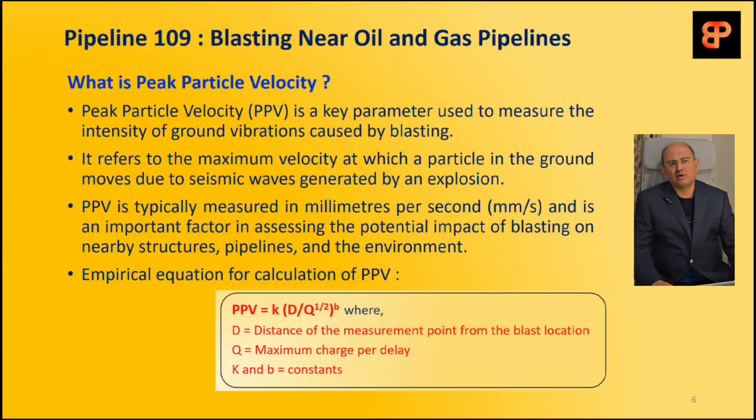Empirical equation for calculation of PPV is given below. Okay, and it's basically proportional to the distance of the blasting site from the structure, building, or pipeline which is point of our interest, and the maximum charge per delay, and some constants which are related to the soil properties of the site.